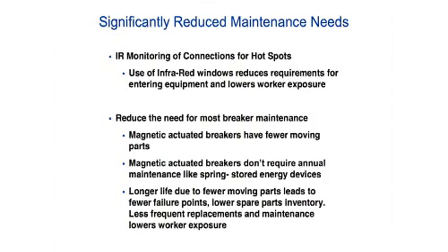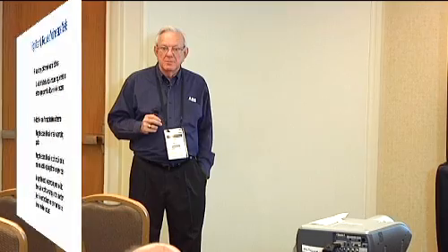Never open up the door. So if I have an IR port and I'm looking in there and I see that things are heating up on a particular connection, lo and behold, I can schedule an outage. Because believe me, you're going to have to take the whole switchgear down to look at this particular unit that's having the problem with high heat.